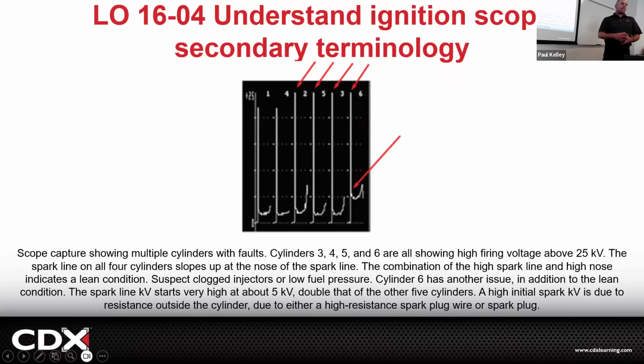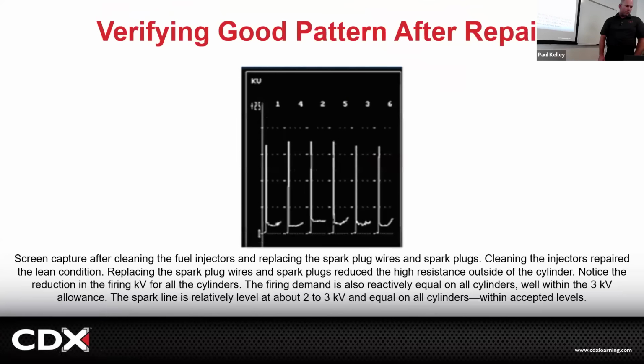That's not usually going to be like a spark plug gap, right? If it's a spark plug gap, 6 would be high on the firing line. The firing line's normal, but the continued burn is kind of high. I think maybe it could be lean. I think it's probably a lean air fuel ratio, because it's harder to keep that burn going when the fuel's lean, fuel trim's lean, right?